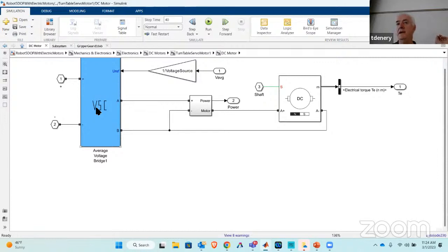It's the basic idea that there's no such thing as a continuous dial that allows me to adjust voltage. If I have a 10 volt DC source, there's no way for me to directly convert that into, let's say, 7.3 volts, right? But what we do is create something that resembles that. Are you familiar with the idea of duty cycle?